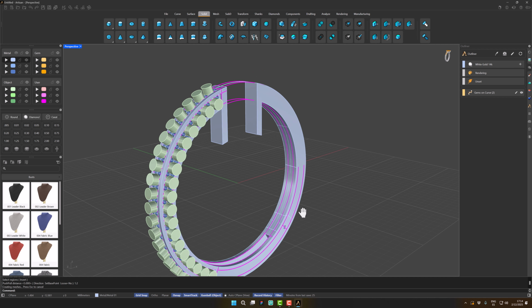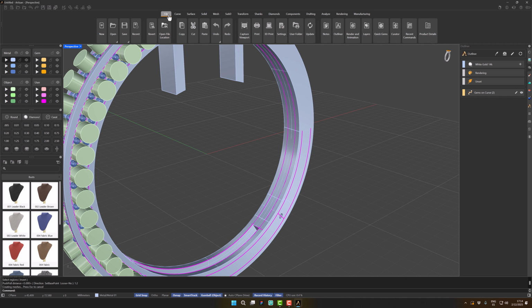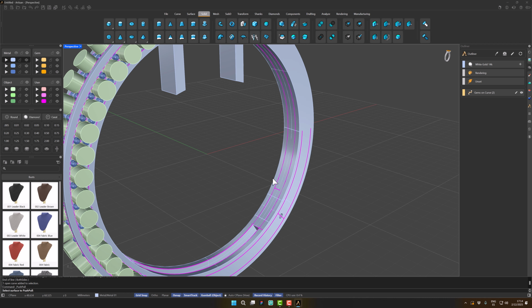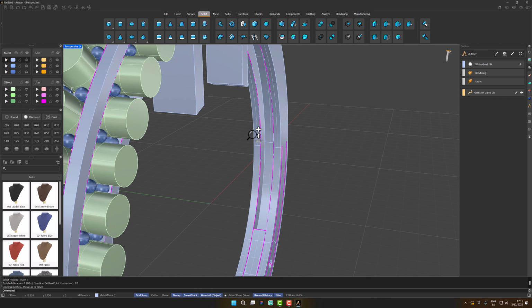We'll create the right side channel similarly. First, draw a margin line. Then perform 2 push and pull operations. Both extrusions should measure 1.2 millimeters. Select the surface, press Enter, move outward, type 1.2 millimeters, and press Enter. Select the surface, press Enter, move outward, type 1.2 millimeters, and press Enter. We're almost done.